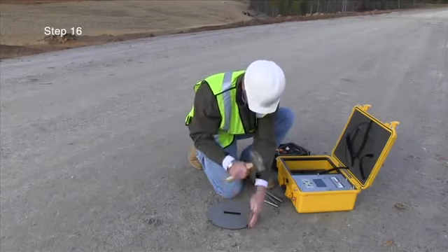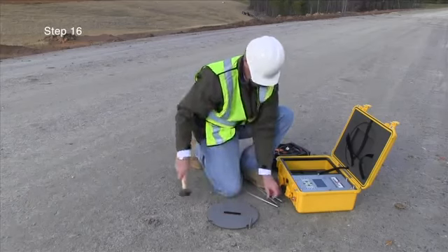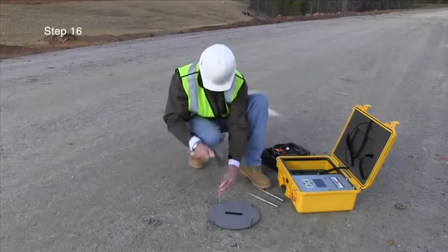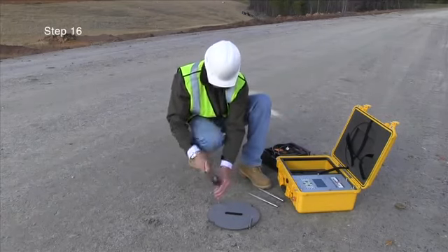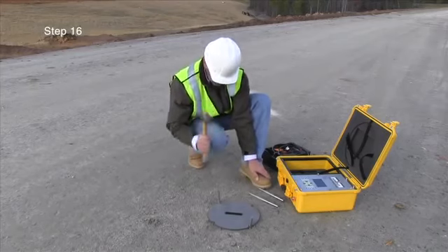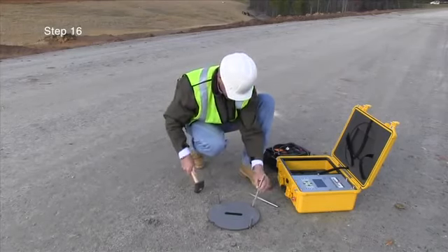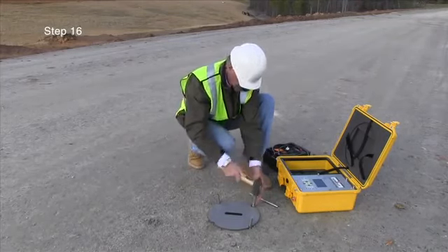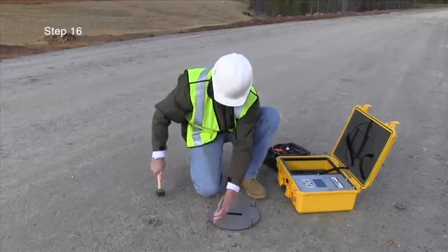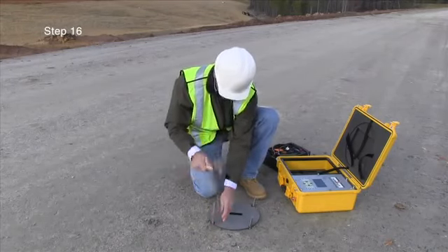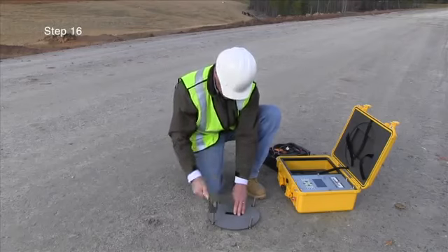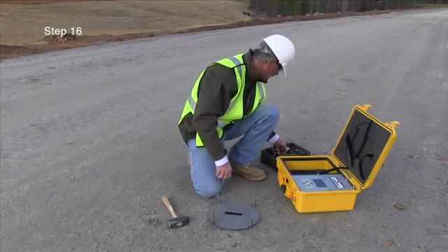Position a dart at each detent of the dart template and hammer into place. The shoulder of the darts should be level with the ground surface. Darts should be driven straight into the ground, not more than 20 degrees from vertical. If rocks are encountered during the process of driving the darts, which prevent the driving of a particular dart, move your test site slightly to accommodate the rock.